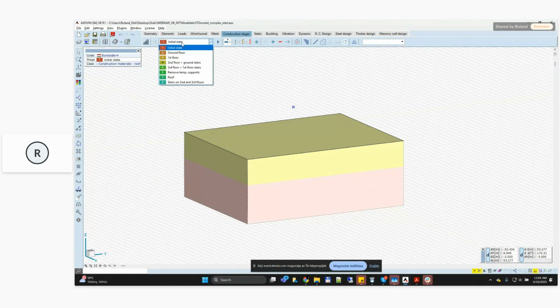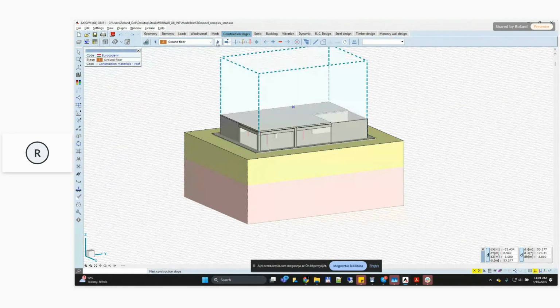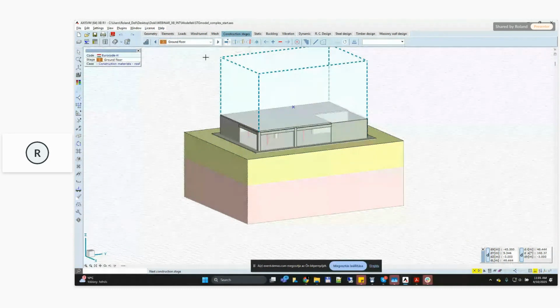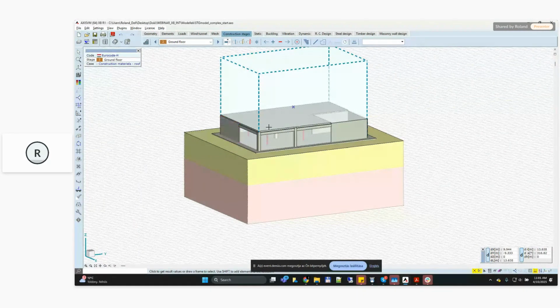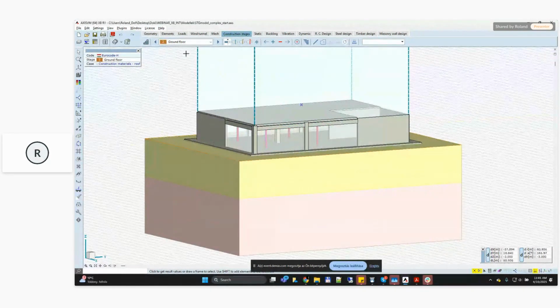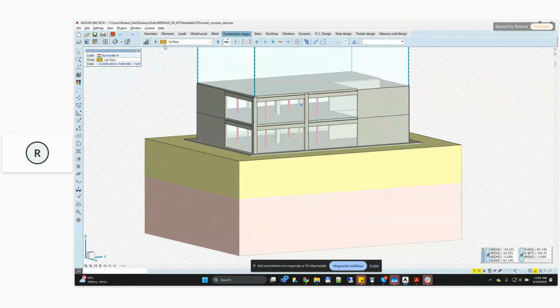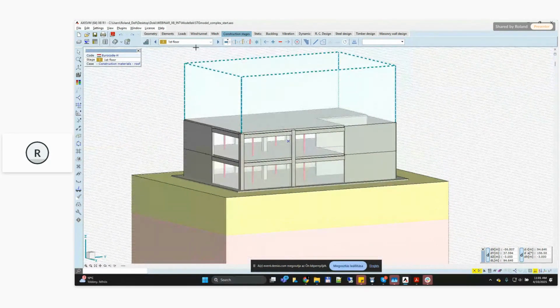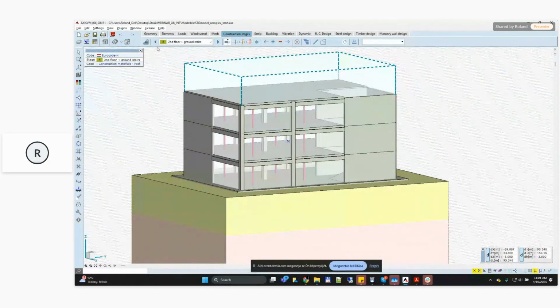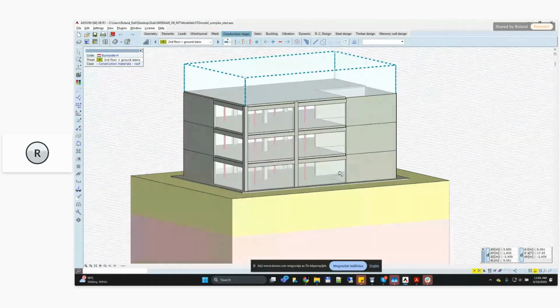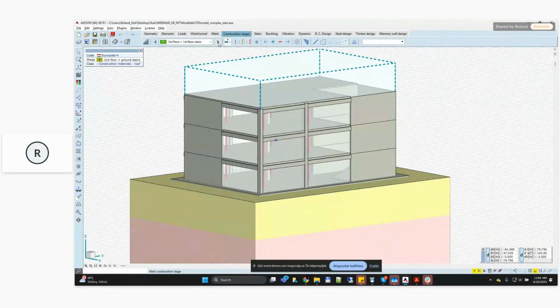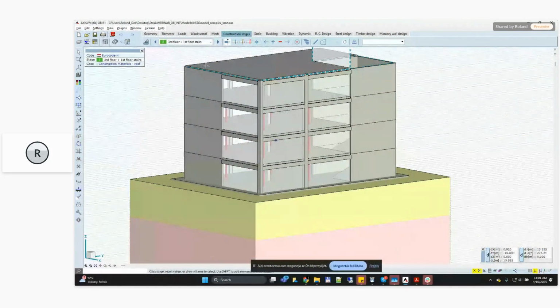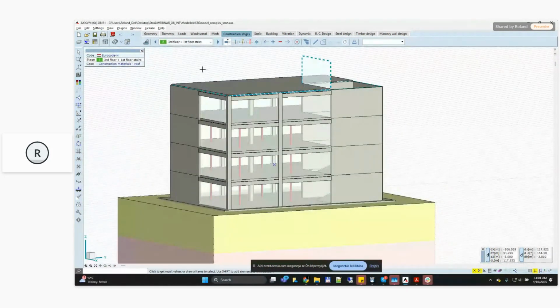So this is why we have used a soil modeling domain in this first state. The next construction stage consists of the ground floor, which includes the slab itself, the foundation slab. We have columns, walls, temporary supporting structure. On the next phase, the third construction phase, the first floor is built, and then the second floor alongside with the first floor staircase. And as we move on in the fifth state, the next floor is being built.